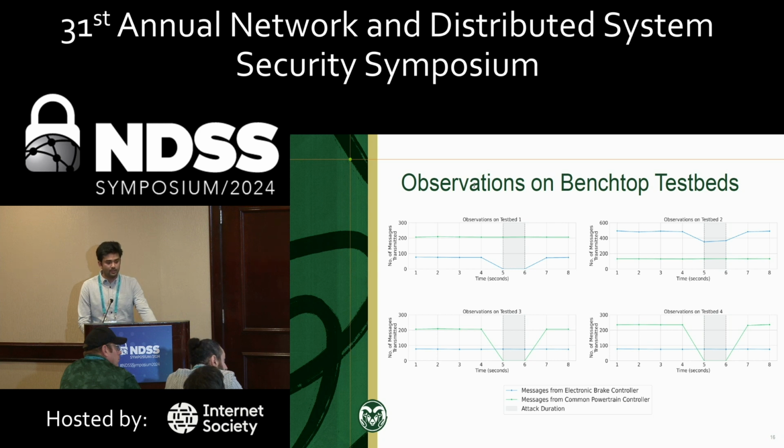The significance of this can be vital because ECUs need some form of periodic transmission. When you have a big truck running on the highway, it's not that the engine just controls everything. The brakes are also responsible, and it's intercommunication that enables the truck to function. It's important for braking functions, it's important for acceleration functions. So if an ECU does not send out periodic messages, the other ECUs may also not work as intended.